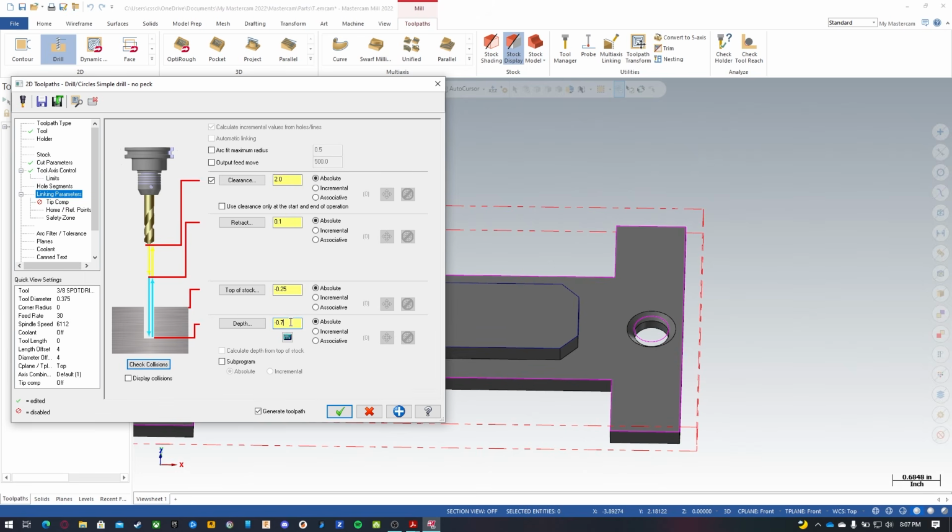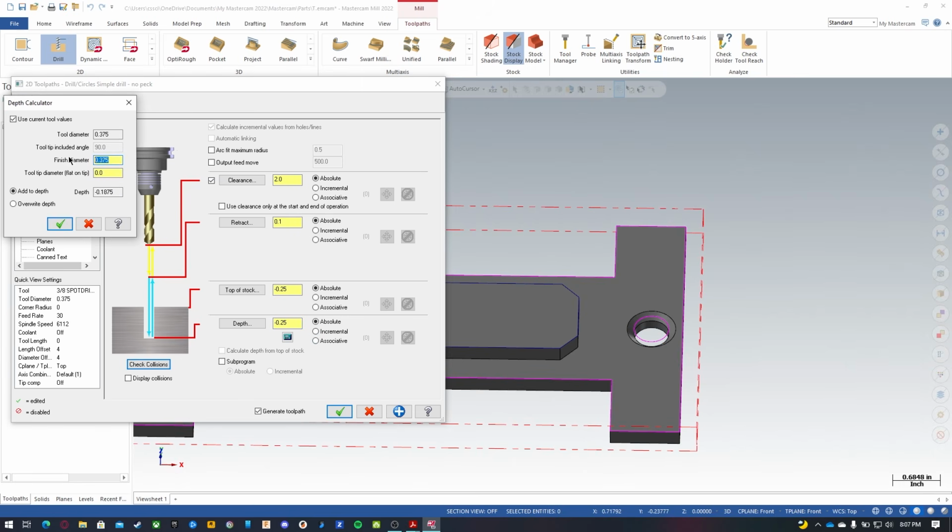we go to linking parameters and we want to go minus 0.25 because that's the top face, and we need a diameter of here. So this hole is a 1/2 inch, but this chamfer is 100 thou. So that 3/8 spot drill isn't going to quite do it. So we'll go in afterwards and do a contour toolpath. You can set them so that if you use this, your finished diameter is 0.875 or 0.975.